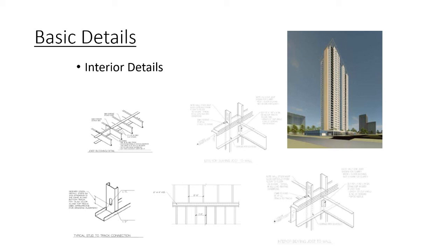The center detail on the lower row shows how to handle the differential spacing from one floor to the next. The upper floor, the studs are spaced 24 inches on center. On the lower floor, they're 16 inches on center. And to adequately carry the load between those two framing spacings, a distribution beam or distribution joist is used in that center line that you see there, horizontal line.